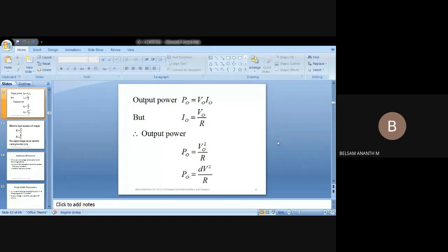So these are the three relations. At least please remember them in your mind. One is the generic power output P equals VI. Next, when you speak in terms of current, P equals I square R. When you speak in terms of voltage, P equals V square by R. Have you got my point? The suffix term, don't confuse that. The suffix always depicts the output terminal or the input terminal, but the meaning should not change. Try to understand, either if you apply Kirchhoff's voltage law or Ohm's law, the equation structure or the notation might change, but the meaning should not change.